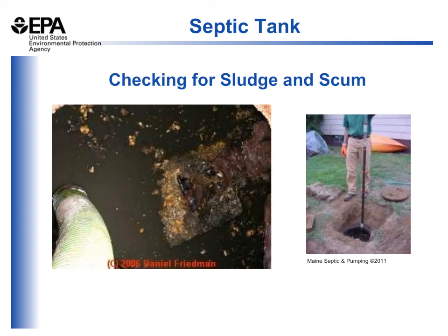It functions very similarly as a straw does when you stick it in a glass of juice or a glass of soda and put your thumb over the top and pull it out. It pulls out the liquid that had been collected within the straw. This PVC pipe can do the same thing and give you a fairly accurate reading of the thickness of the sludge at the bottom and the thickness of the scum at the top of the septic tank. By measuring the sludge and the scum layer and tracking their accumulation over time, you can determine when the optimum time is to pump the septic tank.